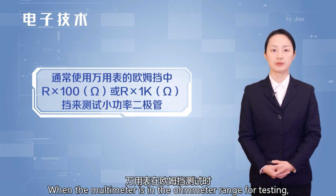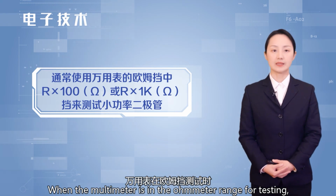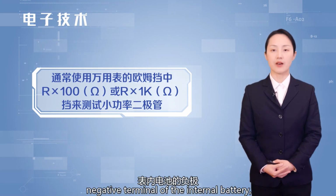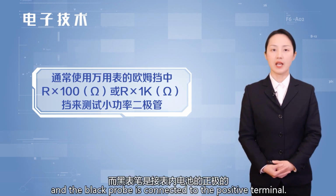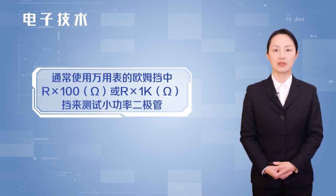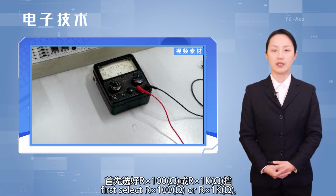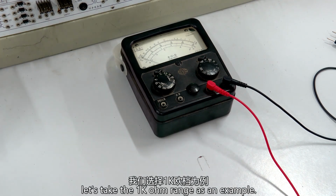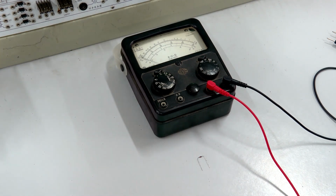When the multimeter is in the ohm meter range for testing, the red probe is connected to the negative terminal of the internal battery, and the black probe is connected to the positive terminal. When testing, first select R times 100 or R times 1K. Let's take the 1K ohm range as an example.